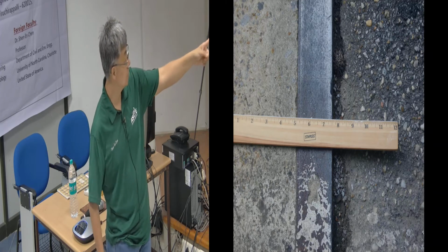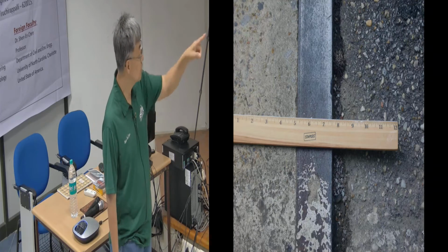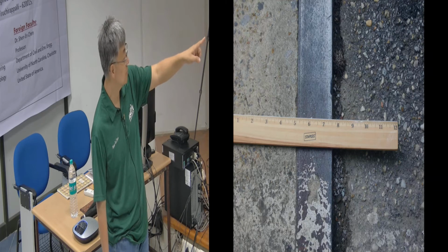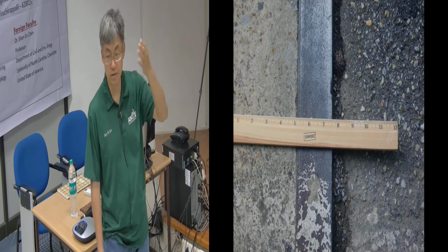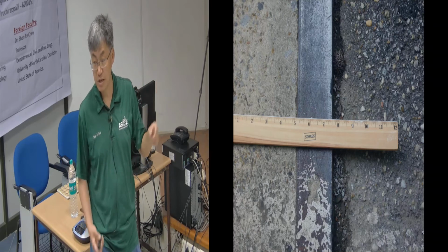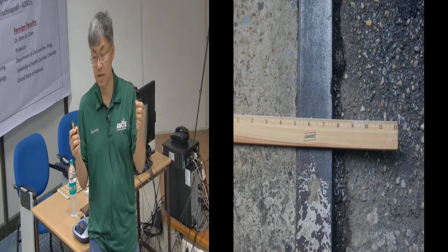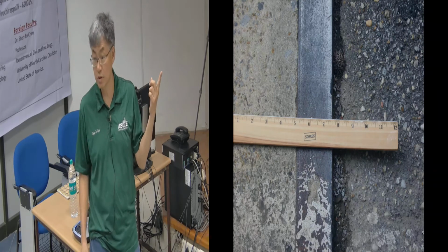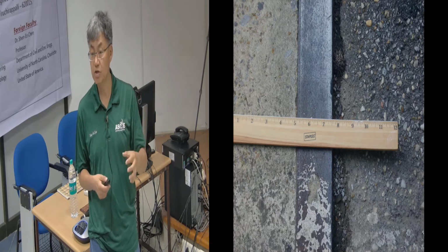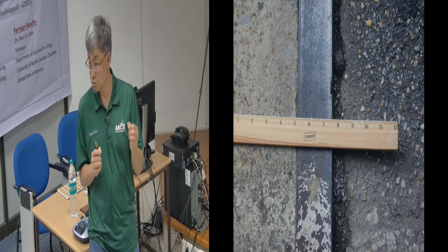Well, this is in inches, I think. So you look at the scale. It has between 6 and 7, for example, there is 20. So 1/20 of an inch is the resolution. And if you use this ruler to measure very small displacements, it will not be valid. So you have to realize that in measurement science, the resolution of your instrument becomes extremely important.